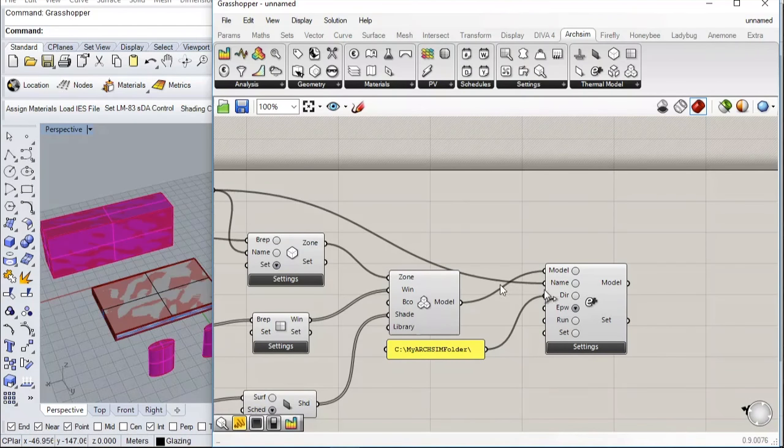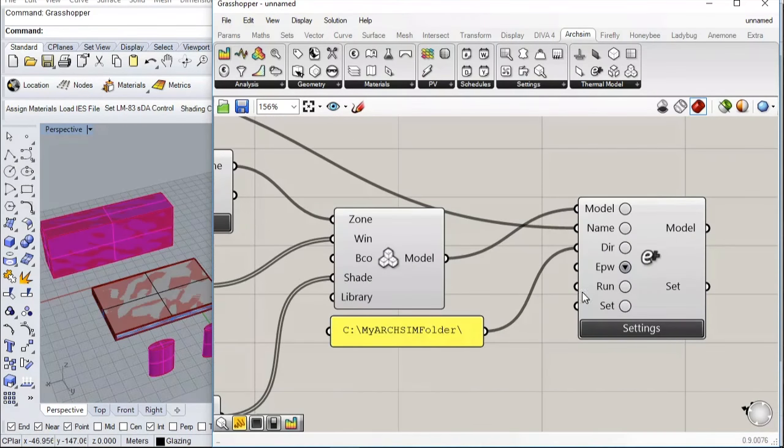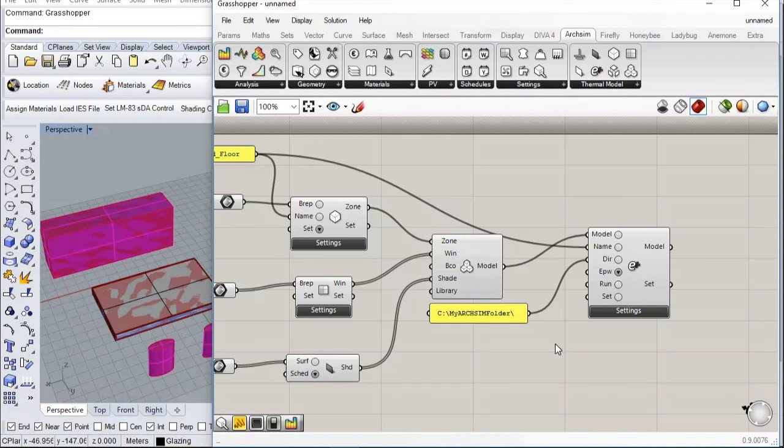That's all we need to set up the flow of the simulation. The only last bit you would want to run, if you create this on your own, is some trigger to tell EnergyPlus to actually execute the entire simulation. There is this run tag here, which is what we want to trigger and turn into a value of true to run the simulation, but it needs some help to do so.